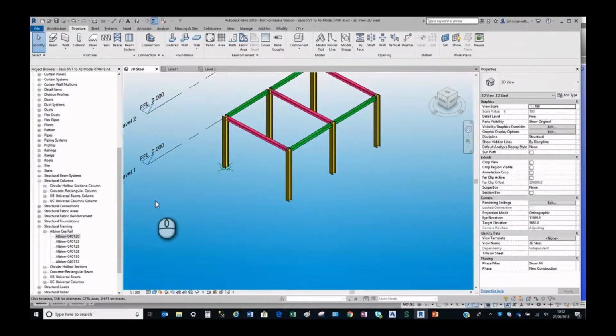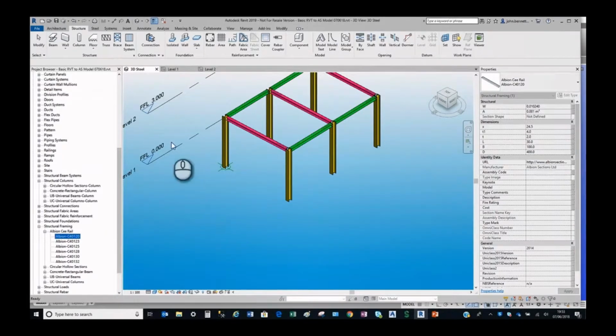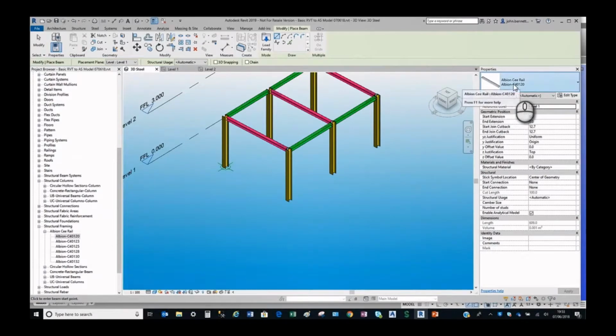So here I'm just going to show that in action. This is going to be using a dynamic transfer button option. Initially I'm going to use a section I found from a cold rolled supplier. I looked on the web, didn't have anything installed. I found this supplier had a particularly good range structured in their system, not just one section with loads of different attributes against it. They actually had each section size, which is what you need to transfer it properly from Revit to Advanced Steel, because we have each beam drawn individually inside the steel database inside Advanced Steel.